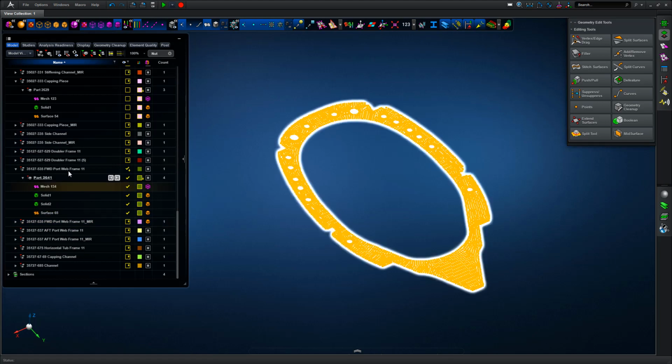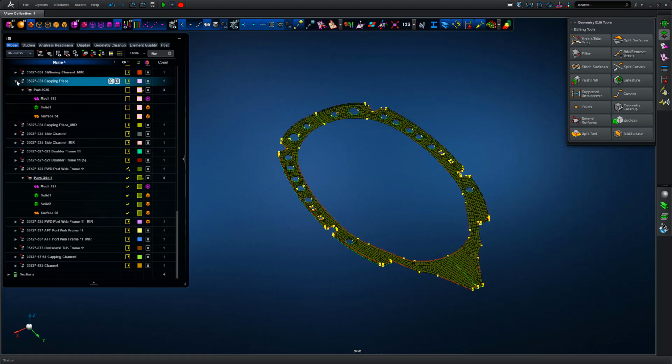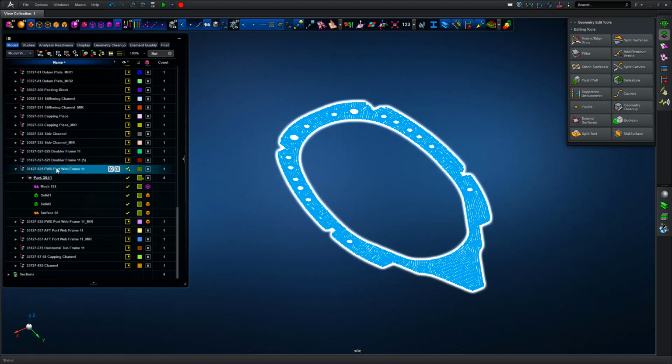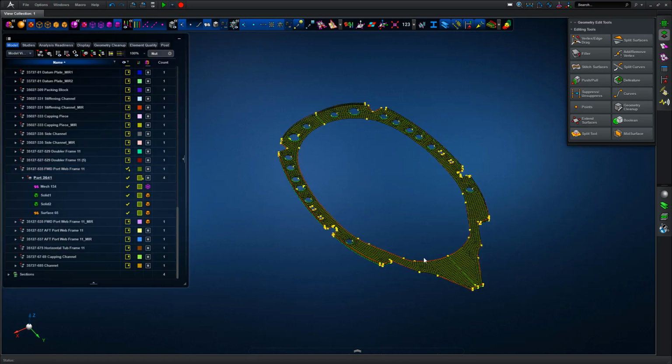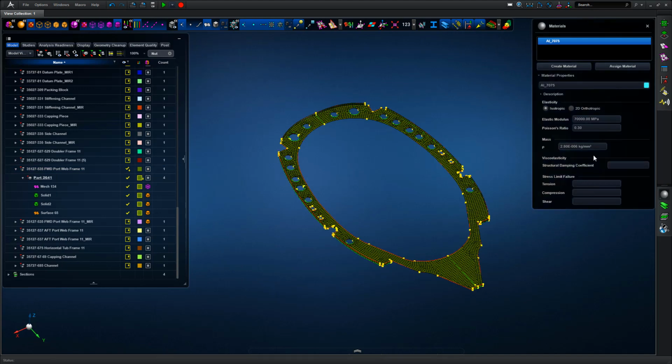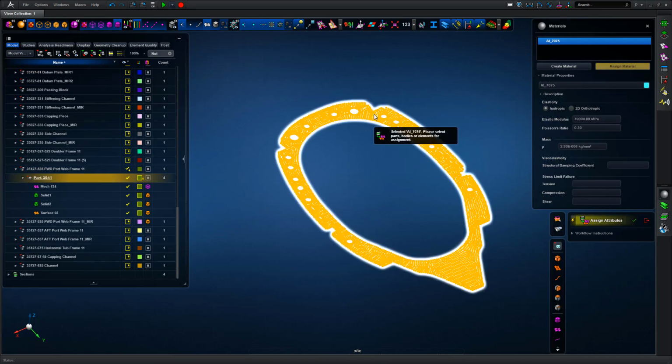This is one of the unique things about Apex, that we can quickly perform a subassembly verification. In the model browser tree, just right click on the subassembly of interest and place in the analysis scene, so that basically sets up the job parameters.